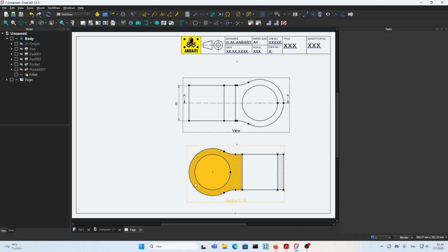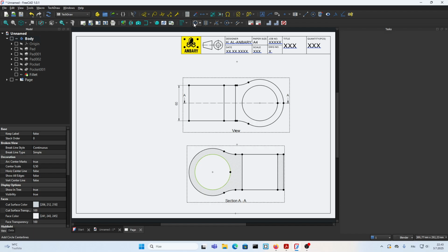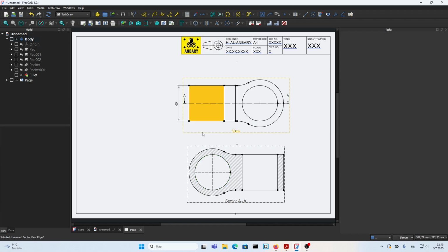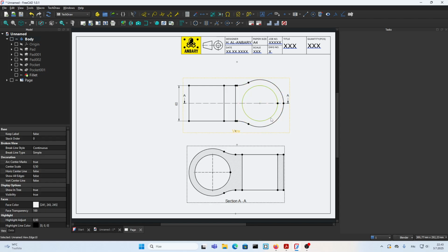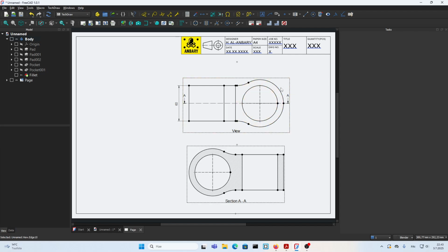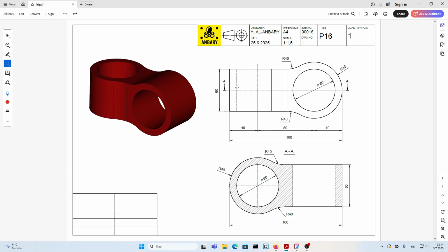From here, choose the circle and click on this, add circle center lines. Now we have these circle center lines added. Same thing, choose the circle and add circle center lines. That's the first thing. Second thing, if you look at my drawing, I have these hidden lines. These are so-called hard hidden lines, which basically show the circle from here, from the inside, as you can see.